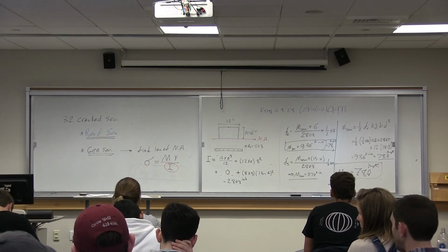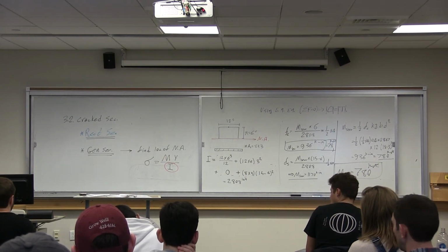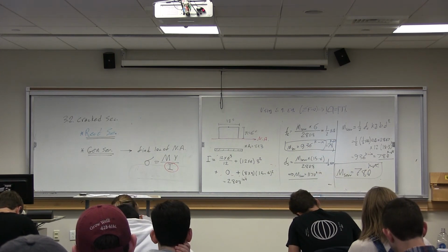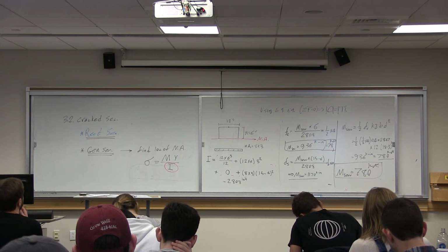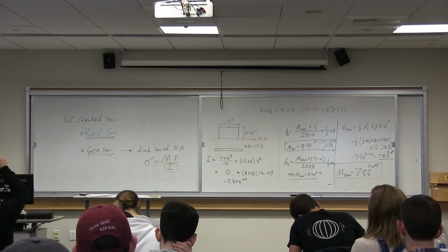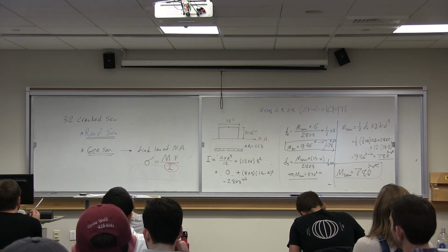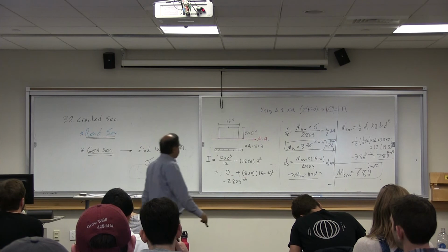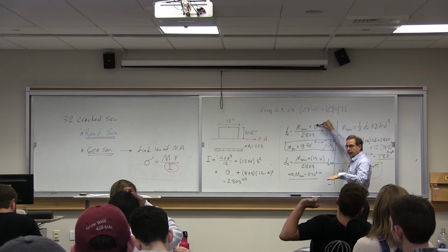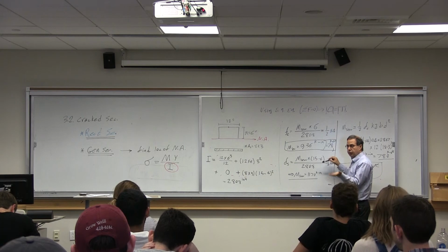The advantage of this method is, if the section is not rectangular, the first method would not apply. I'm sorry, that 15 is the effective depth, the distance between the rebar and the very top. So if we subtract 6 from it, that's the distance to the centroid. In Fc, it's M service times 6. This is 6 distance from the top to the neutral axis. This is 15 minus 6, distance from the rebar to the neutral axis.